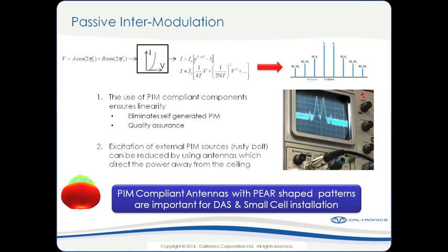This is just something from the internet, but you see two tones, and then on the scope you see the noise floor, and then you see the intermodulation products popping up above the noise floor. This is important because the noise floor is significant, and the amplitude of those peaks relative to the noise floor is significant. Obviously, if those peaks were below the noise floor, then the intermodulation wouldn't be so much of an issue.